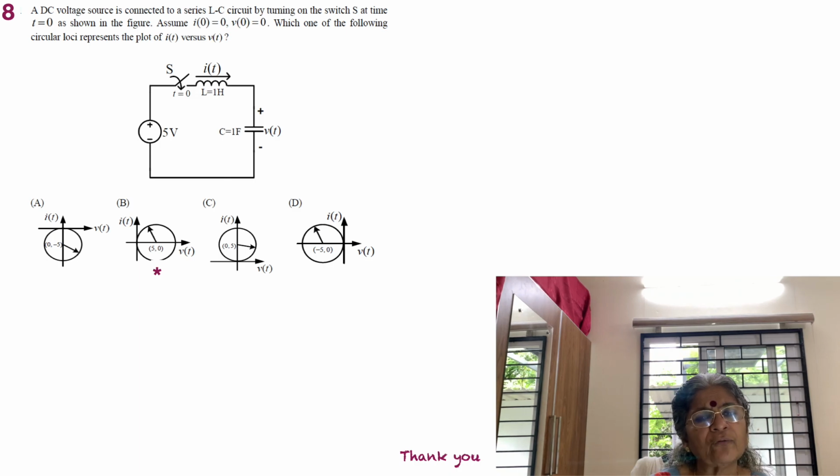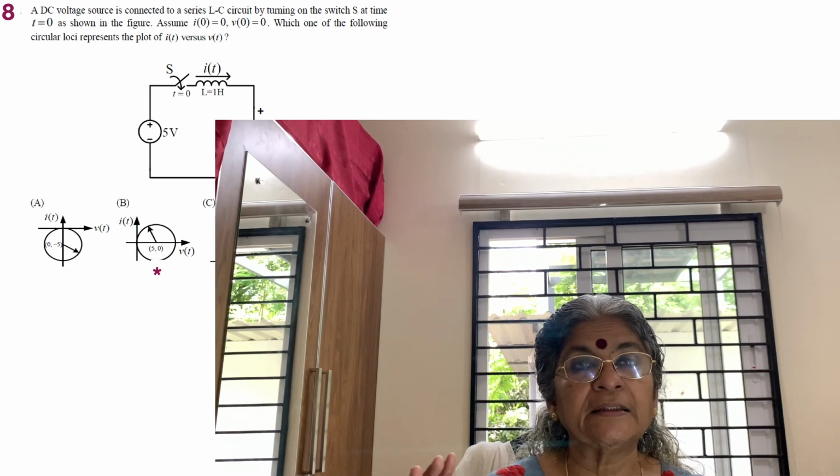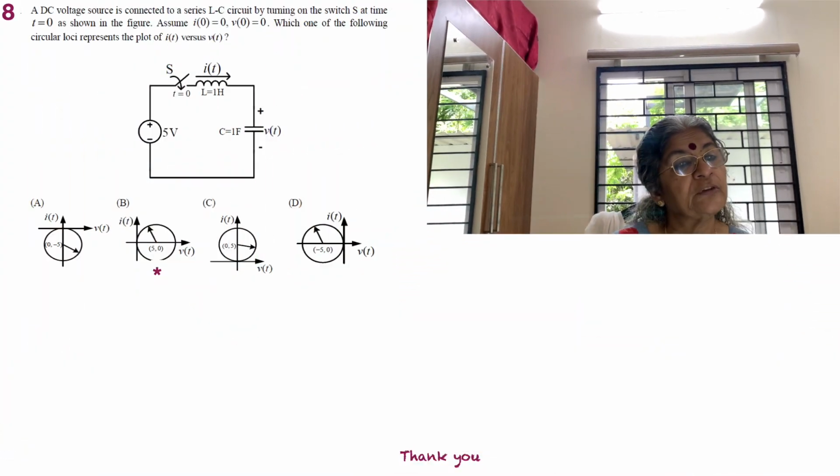Why is it going to get 10 volt? Because when the inductor reverses the current, with the voltages being the same, such that we have a sort of switching, the inductor voltage is going to change. The current direction is not going to change, but the inductor voltage is going to change. So the total voltage applied across the capacitor is now not 5 volt, but plus 5 volt, another 5 volt which is available across the inductor. Okay, so we are having 10 volt here.